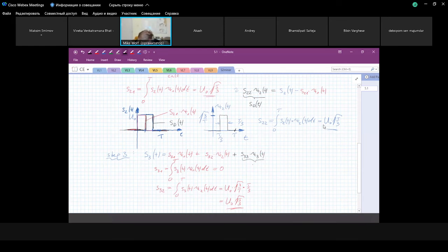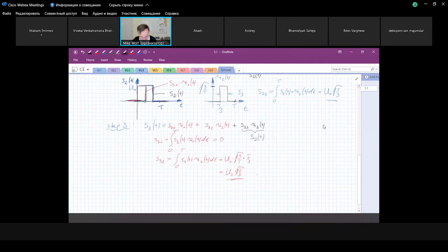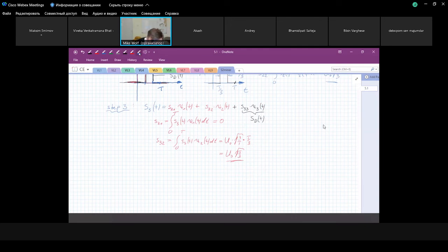And again, we could denote this as the difference signal, difference of t. So how can we obtain the difference signal? We just do the same as before. Maybe I draw it here. Therefore, SD of t is just S3 of t minus the known components, S31 times psi1 of t minus S32 times psi2 of t. And then we have the difference.